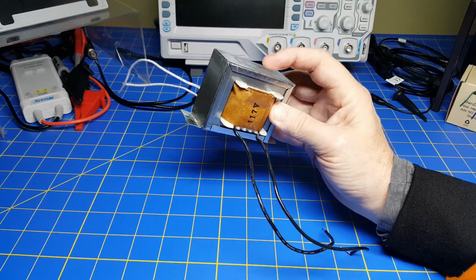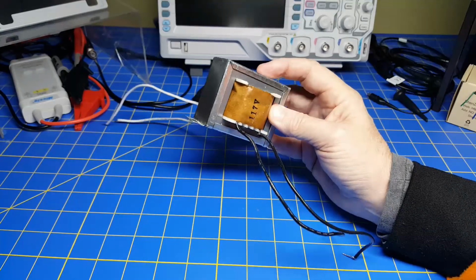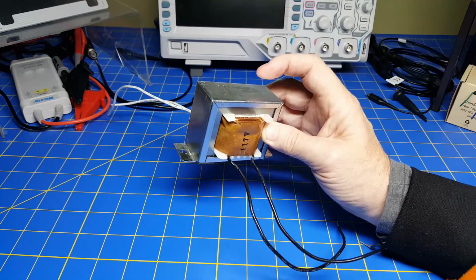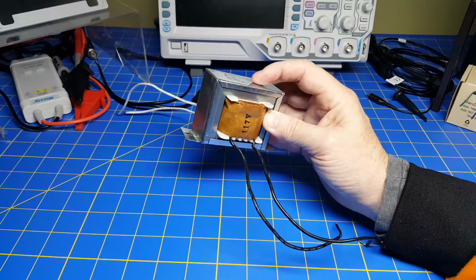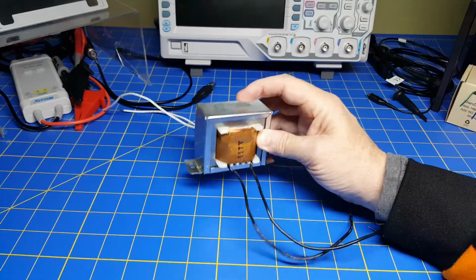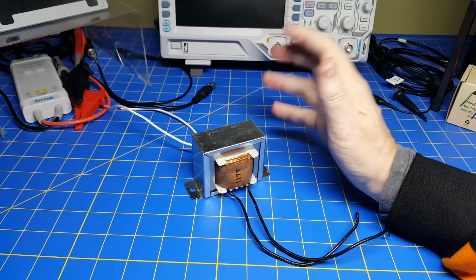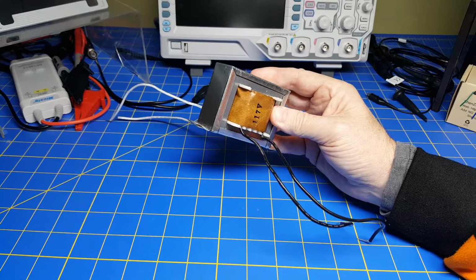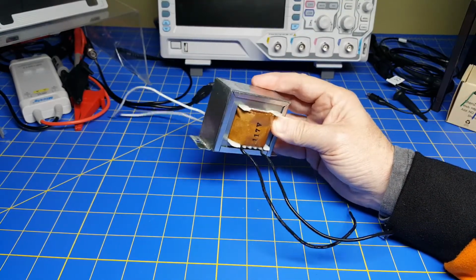If I apply high frequencies, I'm going to have to worry about some capacitor modeling, whereas if I only apply 60 hertz, for example, I can ignore much of the capacitor parameters. So it's very, very important. The first thing you do is figure out what range of currents and voltages and frequencies you're going to be modeling, because that defines what the model is going to look at, how complex or how simple it is.